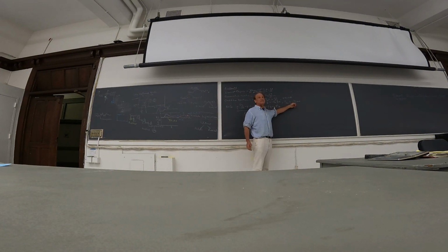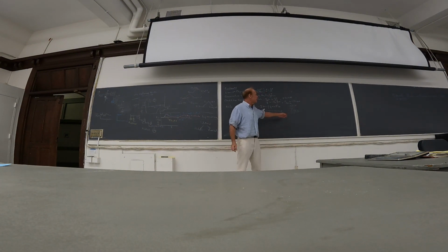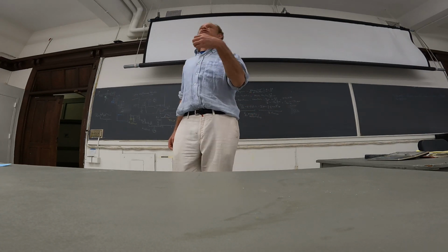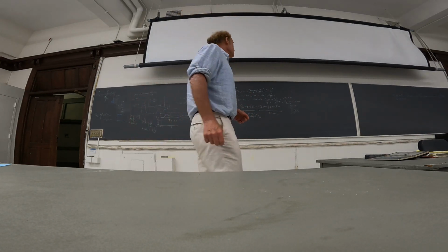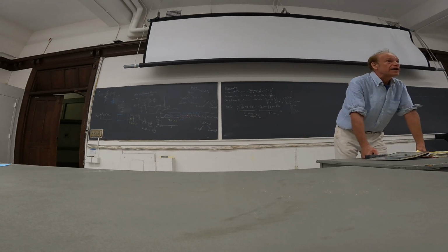This is a linear spring, but I may have springs that are not linear. If you look at springs where the diameter changes, these are nonlinear springs. They don't satisfy this equation. So constitutive equations sometimes hold, sometimes they don't. Laws of physics always hold. That's an important distinction when you're making models.